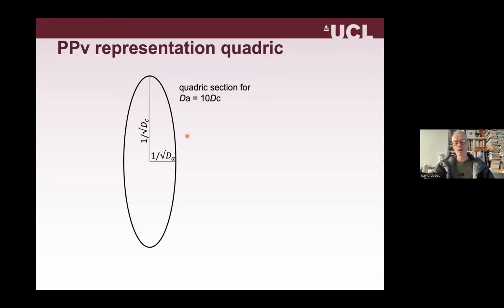And if you want to know how any particular flux will orient with respect to a chemical potential gradient, you draw the gradient centered on the center of the quadric. You then draw tangent planes to the quadric where the gradient is touching the quadric, and at right angles to that, they're the fluxes that you get. Okay, so if you have a higher diffusivity in a direction, then the fluxes will tend to be towards that direction than towards lower diffusivity directions.